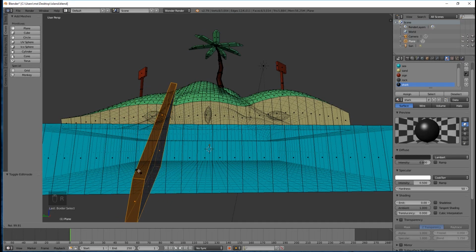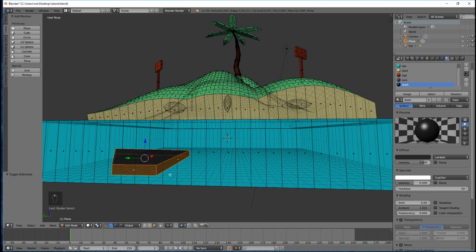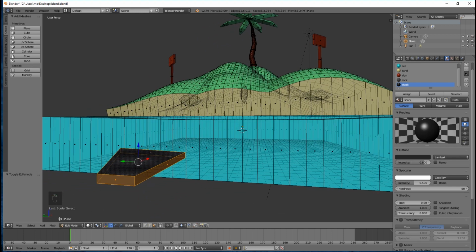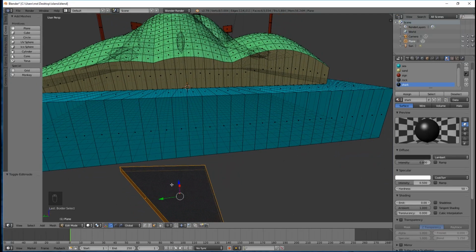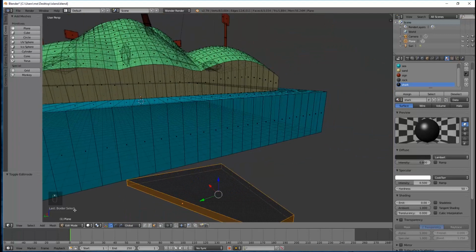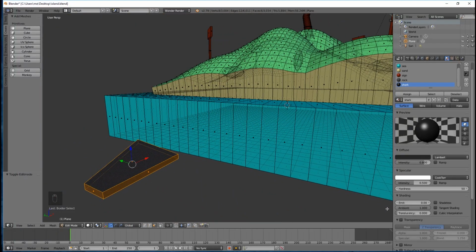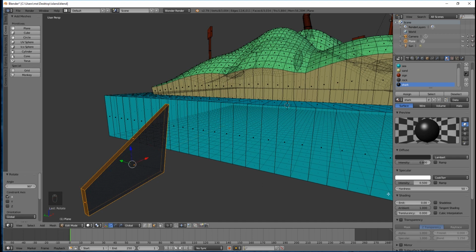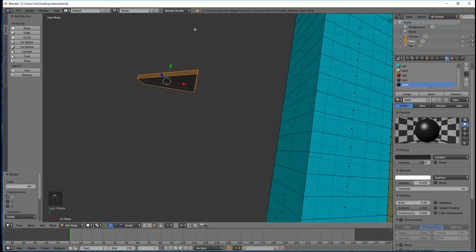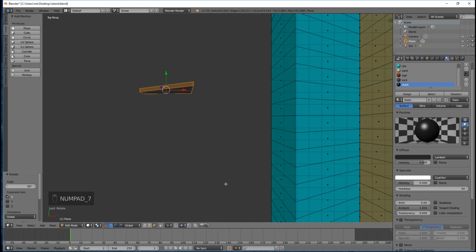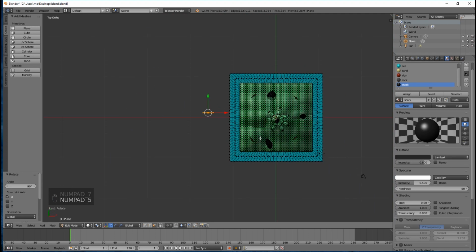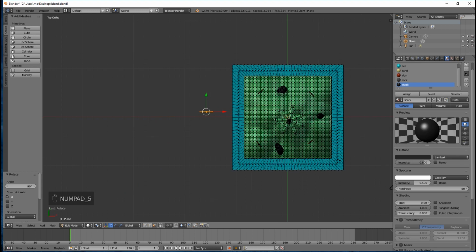And in fact, it's rotating in two different axes. So what I'll do is rotate along the red axis there, which is the X axis. So I'm going to press R, X, 90, and then press enter, and that's rotated at 90 degrees exactly, so that's fine. Right, let's look down on my scene again, take off perspective, and I don't need the limit selection now,